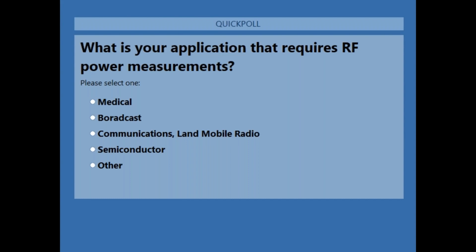The ones that come to mind immediately for me are going to be FCC limitations on irradiated power, so making sure you're within some sort of legal operating range, you're not stepping on anybody else's toes, and generating too much power that might be interfering with another signal. Making sure that while you're staying within those legal bounds, you're getting the maximum power delivered to your antenna, so you can help to ensure proper coverage area.